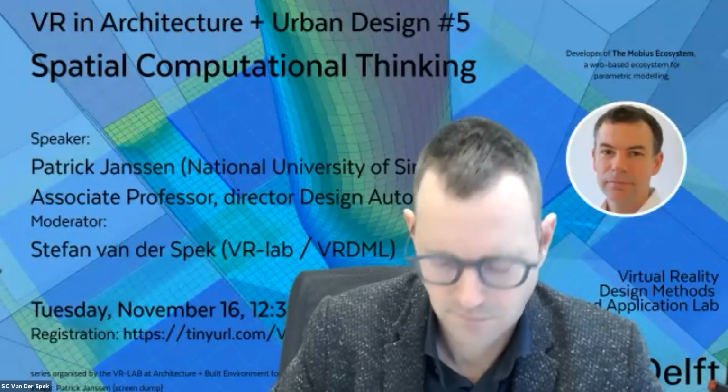So these attributes become a powerful technique for doing all sorts of operations. But especially, we always use the attributes for selecting stuff. When you have multiple nodes and you're writing a script in one node, the next node in the system will retrieve the geometry using attributes. The previous node will create an attribute called, you know, type equals wall, and then in the next node you say, get me all the walls and do something with them.